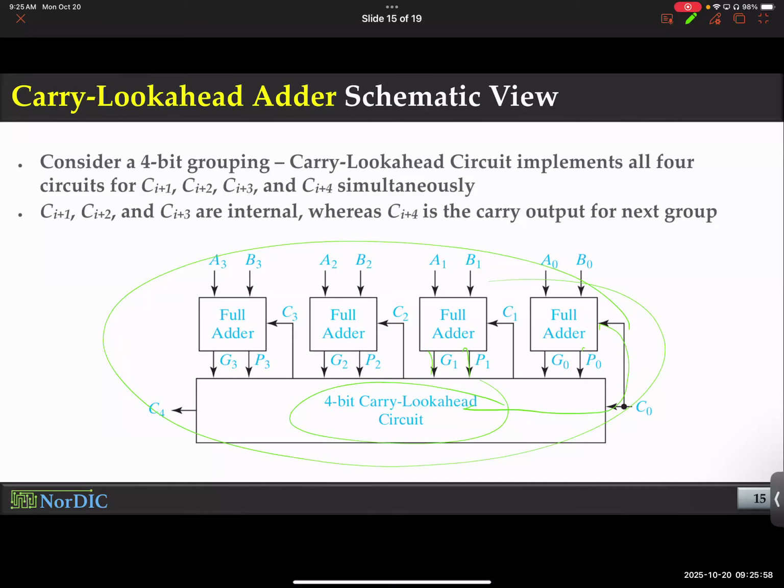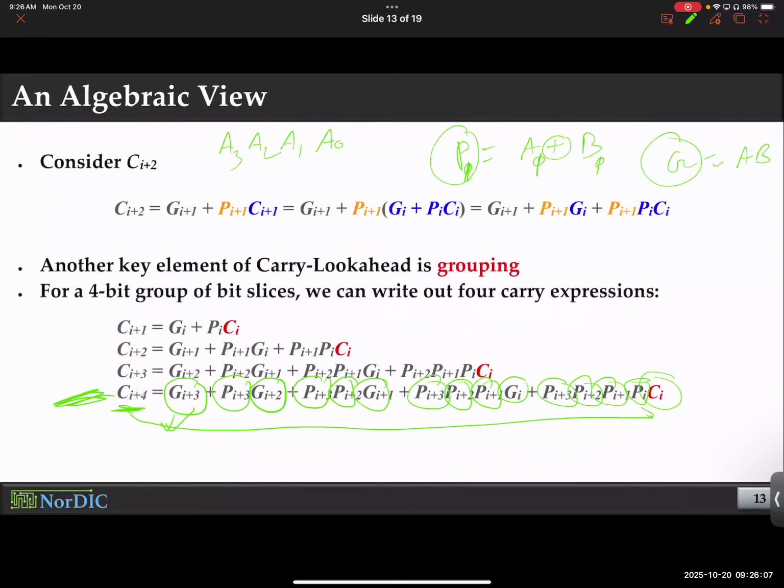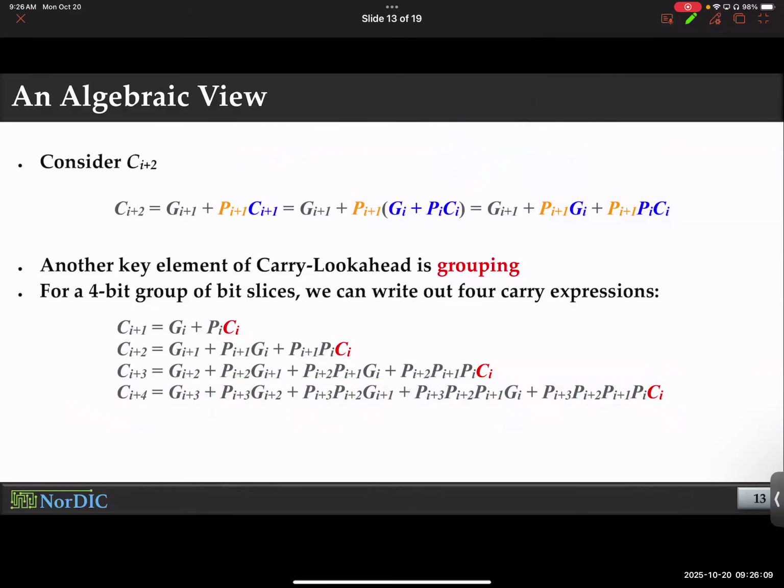Yes. Thank you. I was just waiting for you to ask this question. Hold on a second. Just to pre-calculate this carry, just look at the complexity of the function, right? Don't you think? How many AND gates or OR gates do you need to incorporate that? This is easily 1, 2, 3, 4, 5 input AND gate, and then you have a bunch of OR gates. And this is just the fourth carry. Imagine you are trying to add a 32-bit number with another 32-bit number. Can you even imagine the complexity of the logic, right?